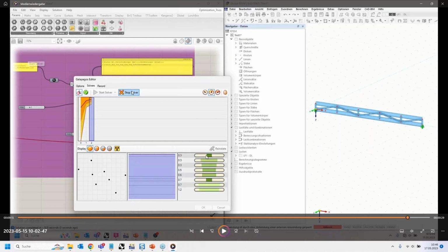reinitiate this specific situation. So you can click on this variant where the result was 0.3 millimeters and say, give me the input data from this variant, and then you can call up exactly this situation in Grasshopper and basically also in RFEM. Or if you say, I want for some reason the structure where it was 0.5 millimeter, then you can click on this one, say initiate, and then you get the structure where it was 0.5 millimeter in the deformations.